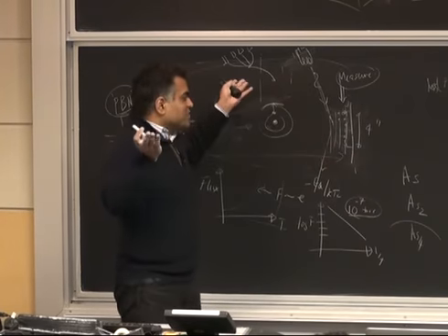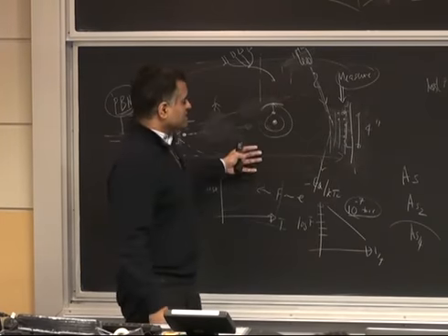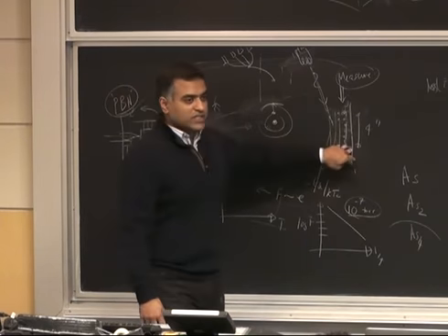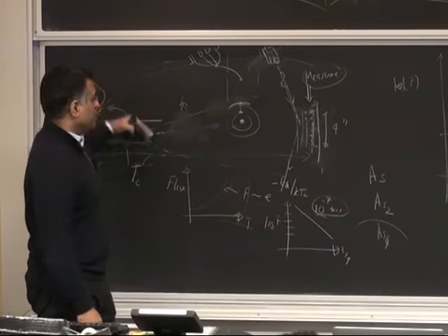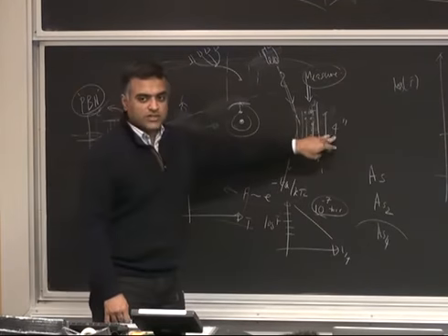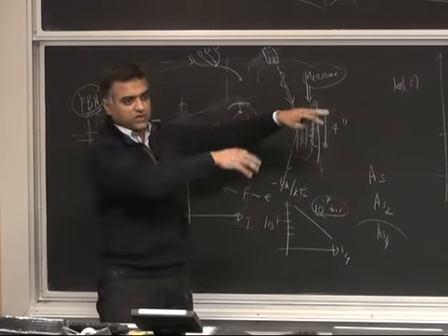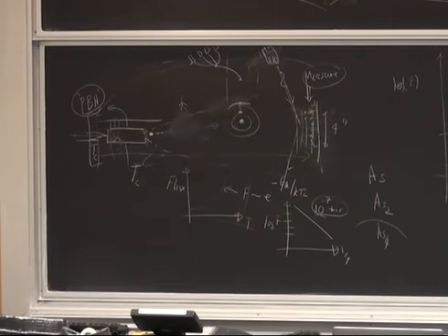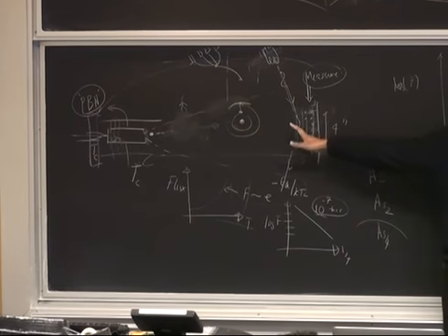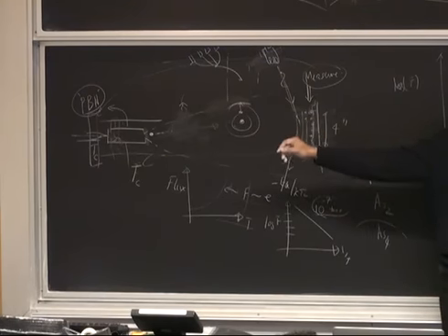Basically you have two or three control parameters: the fluxes, and the temperature. That's all you control. There are like three knobs: how much gallium, how much arsenic, and what the temperature is. And the pressure, of course. Within that, we'll see there's a very small window which thermodynamically and kinetically makes it possible for you to grow a crystal. If you're very far away from there, you won't grow a good crystalline solid. You will have something else. That part we'll start looking at in the next class.